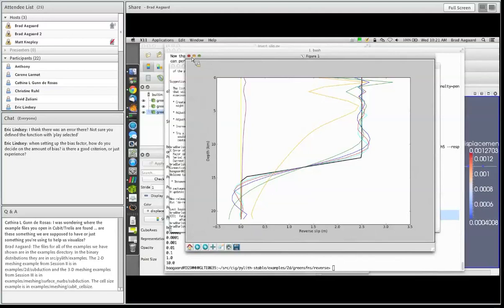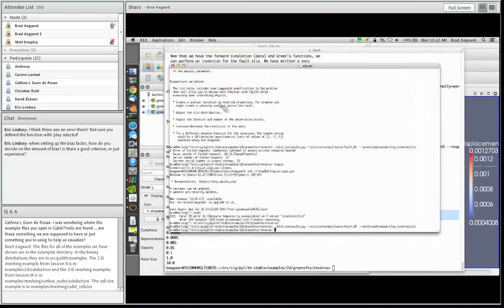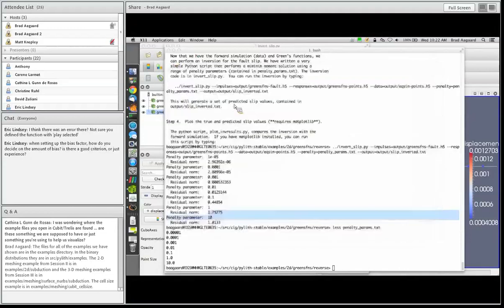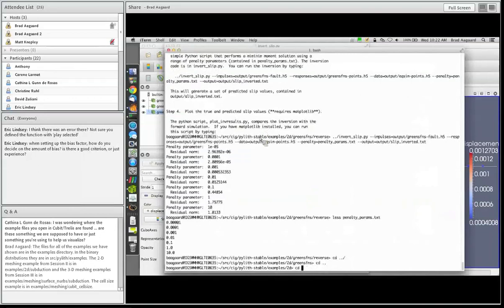We're going to look at greensfunctions.cfg. So remember our pylithapp file here, I'll just flash it up momentarily. It set all of our basic parameters for all of our 3D Hex 8 simulations. It would specify in our journal output, it specified where our mesh file was coming from, and it specified our elastic properties. So we're using MatElastic as the default.